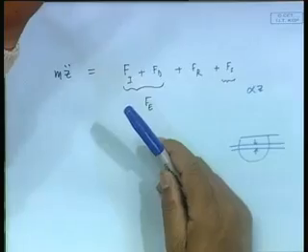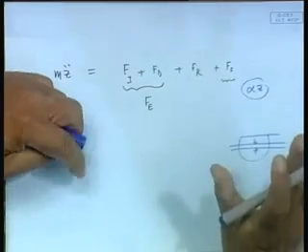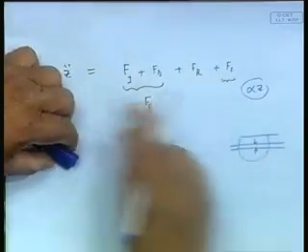What is roll? If I give a phi, what is my restoring moment? It is rho g V into zz. What is zz? For small angle, GM into theta. So it is rho g V GM into theta. So again it depends on theta, the displacement. So this is proportional to displacement in this case.